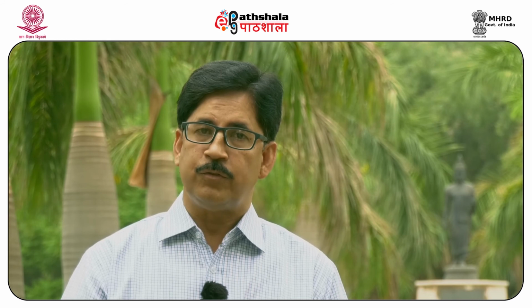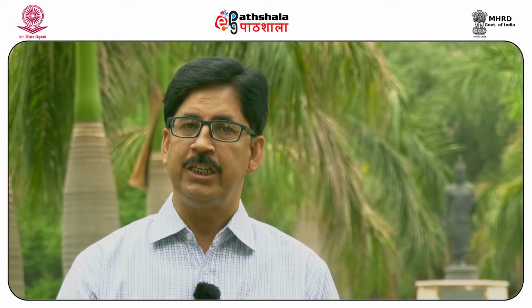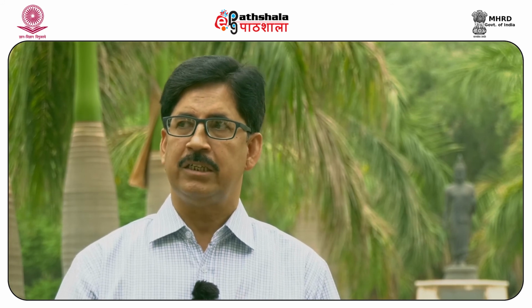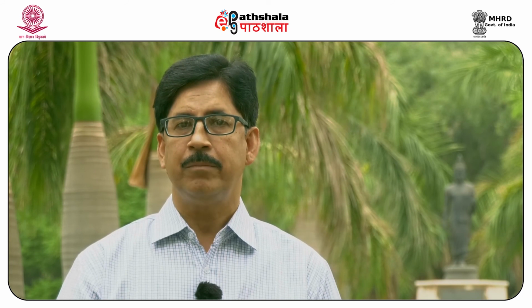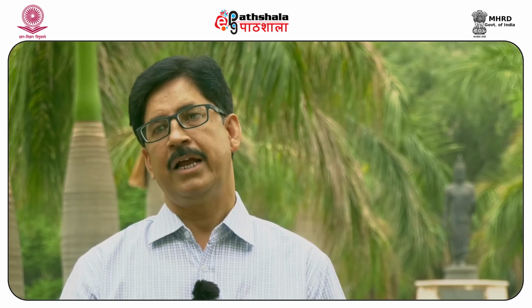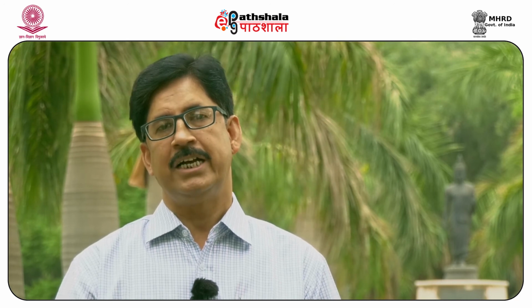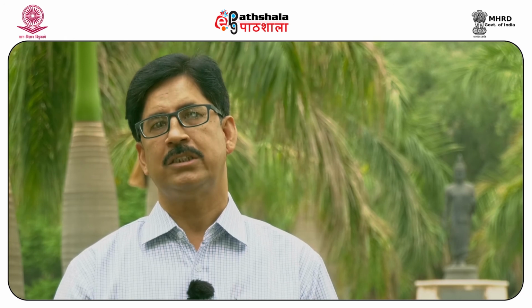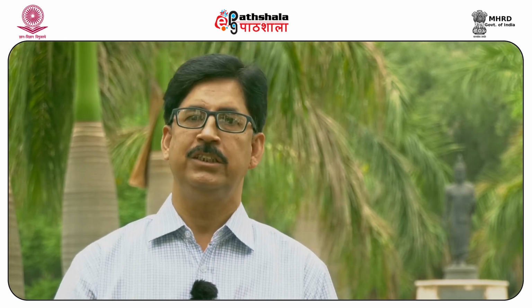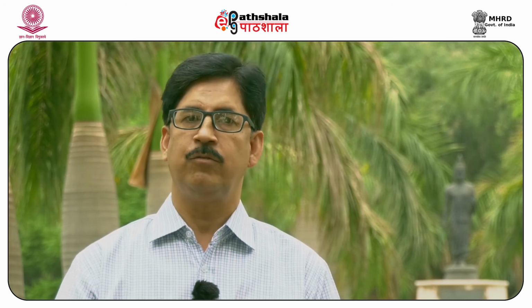Shear zones may be present occasionally in the rock mass. If you can find them, it is better to hack them out, excavate them and fill them with concrete. Shear zones are avenues of groundwater, and groundwater is not good for any civil engineering structure. So is the case with faults and fault zones.